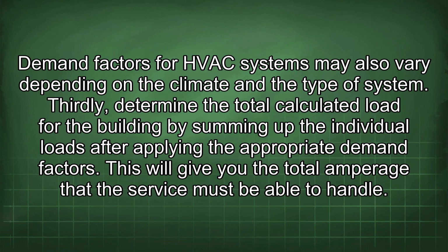Demand factors for HVAC systems may also vary depending on the climate and the type of system. Thirdly, determine the total calculated load for the building by summing up the individual loads after applying the appropriate demand factors. This will give you the total amperage that the service must be able to handle.